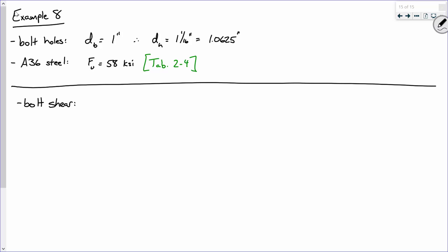Now, remember we've got our handy-dandy little A in the middle of the manual, right? So we're going to Table 7-1. Remember this one, available shear strength of bolts. Now, which numbers are we looking at? Green numbers or blue numbers? Blue numbers. There we go, LRFD. So tell me what I need to know in order to properly look up values for this connection. What type of bolts do we have? Group A, Group B? Group A. And then that's included or excluded.